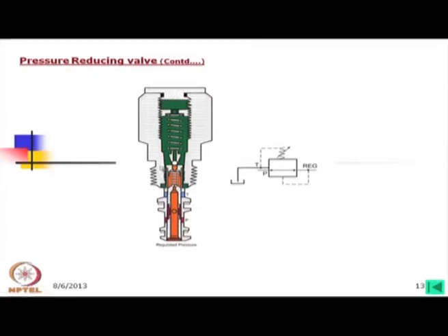Now, this whole thing can be mounted on a manifold. Simply this is threaded to there and there are cavities. As you see this groove, there will be an orifice. So, this is one chamber and there will be another chamber where the oil can go to the tank, and then this is directly connected to the regulated flow side. So, this is a cartridge type, but as you see this is a fixed one, this cannot be regulated.